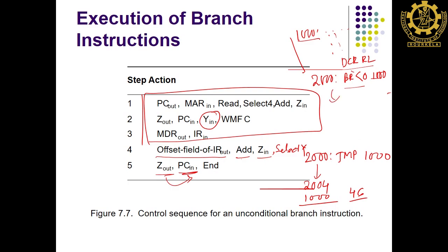Actually, for any operation there will be a status bit. Okay. So, status bit means there will be a special register called the PSW, program status word. The program status word has, let us say, 7 to 8 bits. If the result is 0, there is something called the Z bit, it will be 1.